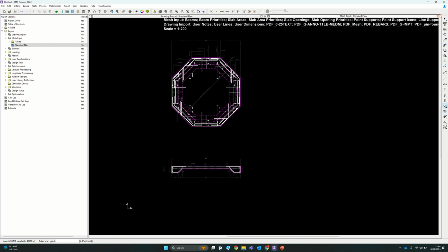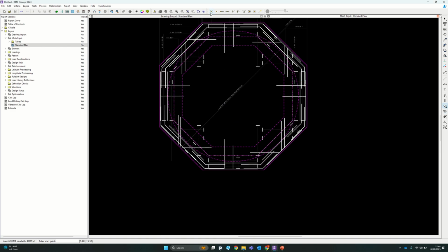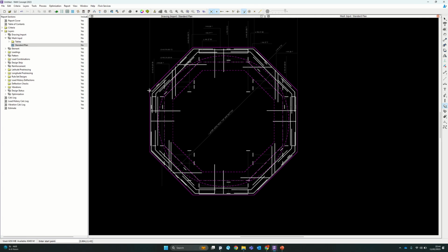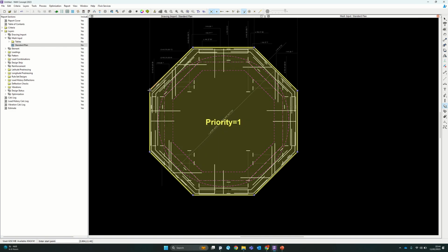Anyway, up at the top here, we've got snap sends, intersection, node, endpoints, midpoints, nearest, that's obviously if you're going along the line, perpendicular, no orthogonal even, so that keeps it going in X and Y, and perpendicular, we're going to take that orthogonal off, and then center, etc, etc. So simply modeling this then, just grab a corner, corner. This is very rough and not that accurate as I'm just skimming through it.